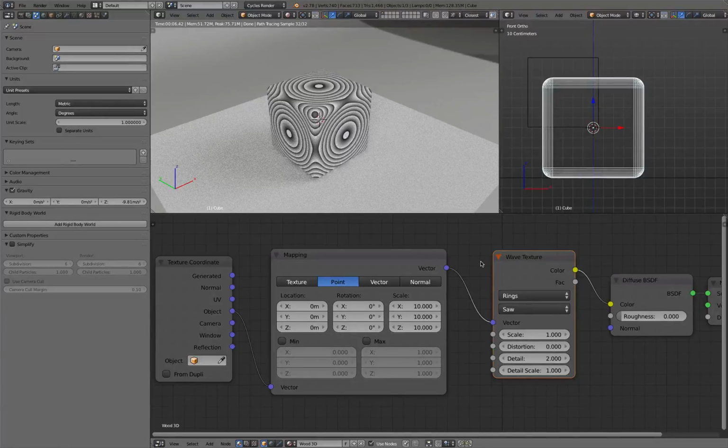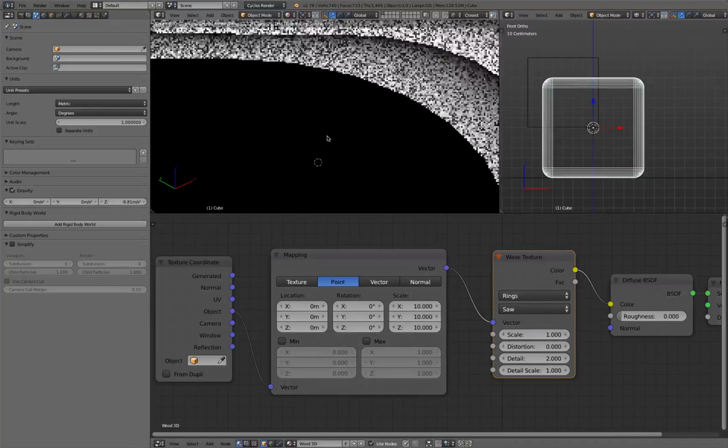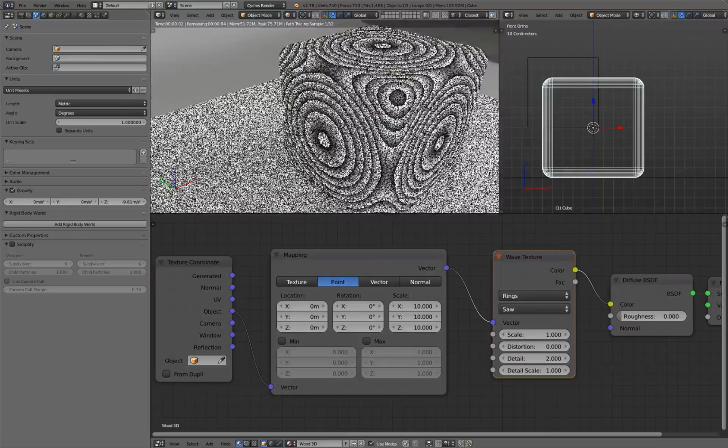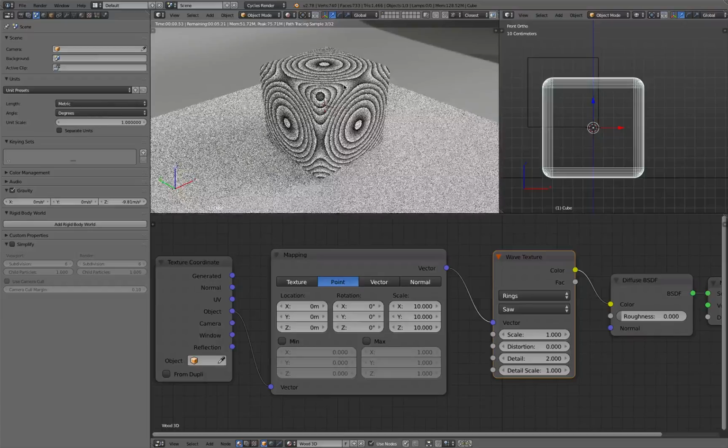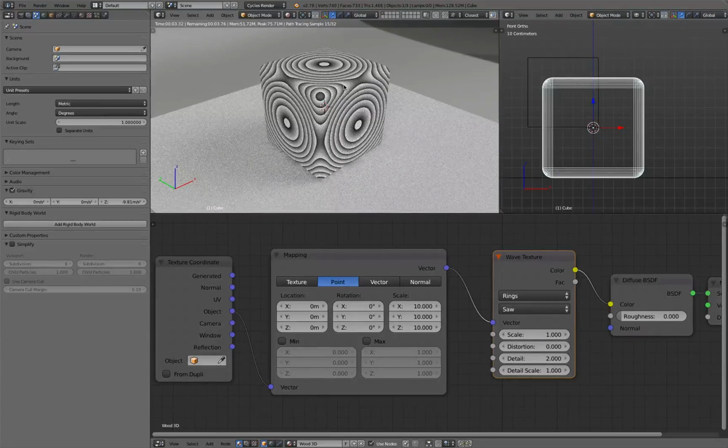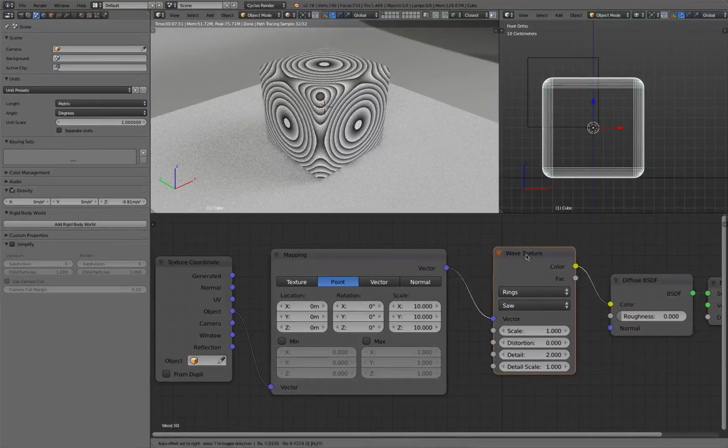I also said procedural texture. So what does it mean? An image is two-dimensional, so it's a pixel-oriented texture. But a procedural texture is actually math code that just generates the look for me, because I can zoom in as much as I want and it will always be nice and sharp and crisp. And you know, with images, when you zoom too much, at one point you see the pixels popping up. So the advantage of those procedural textures, like the wave texture, is they are resolution independent.